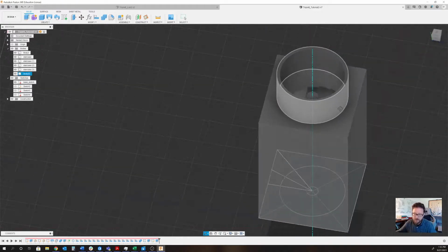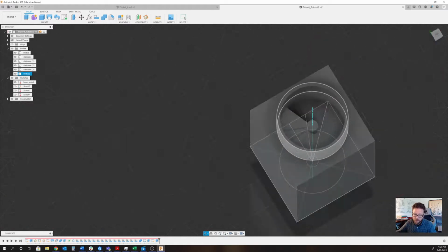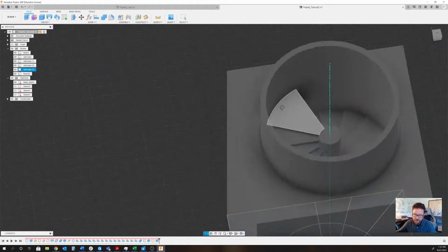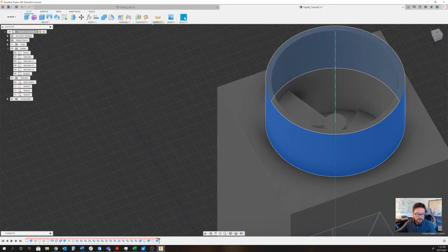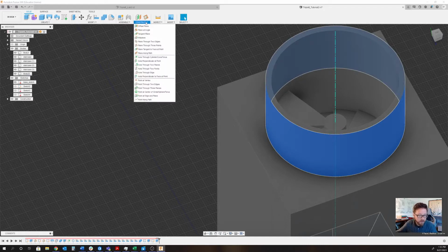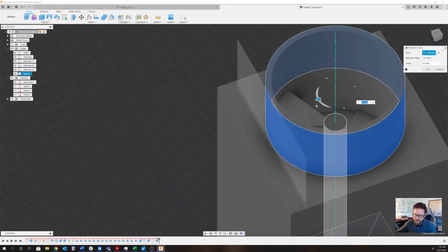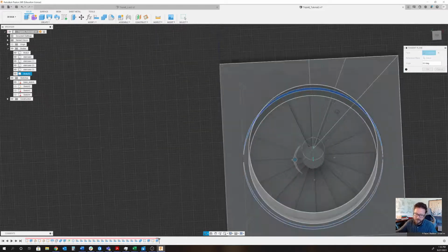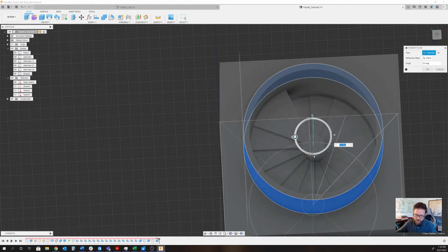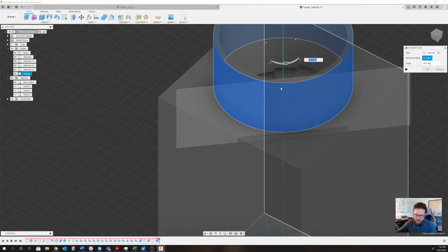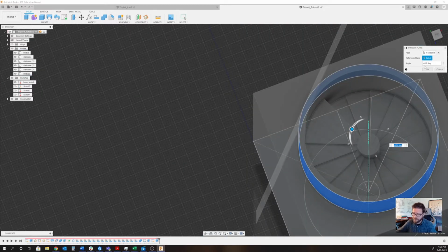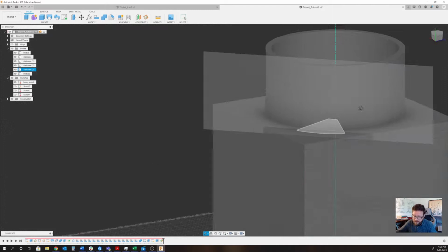What I really want to do is create a doorway in here at the very top stair. So that's actually quite easy to do. Another construction plane you can create is what's called a tangent plane, and I've got this attached here. For me, it's pretty clear that this is going to be about 45 degrees out. So at 45, if I draw a doorway here, it'll reach the top step. So that's fine for me. Maybe slightly different for yours.